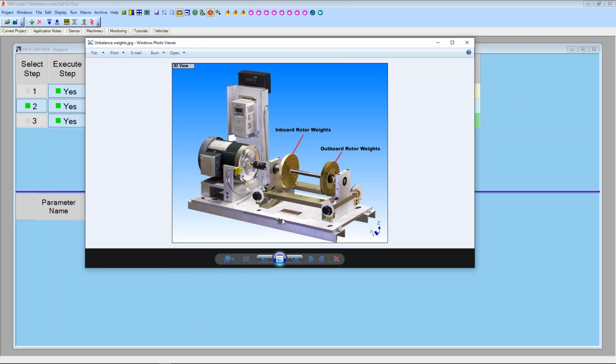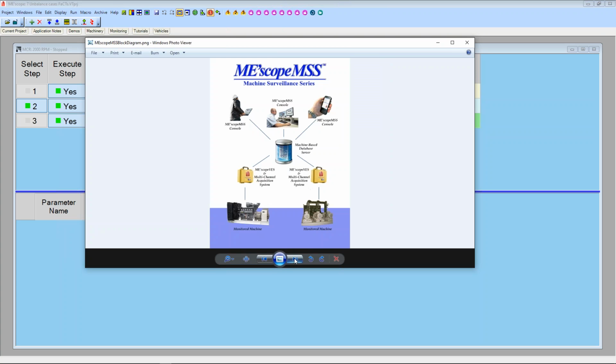And what we're going to do is simulate unbalanced cases by putting, we have done this, small screws onto either the inboard rotor or the outboard rotor to cause specific unbalanced cases. And then we measure the ODS and compare that with the known ODS of each unbalanced case, and we can use the facts calculation to identify a specific case. So a lot of things going on here.